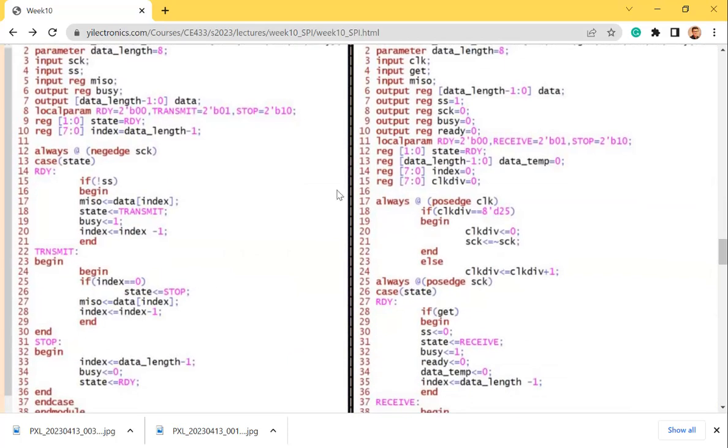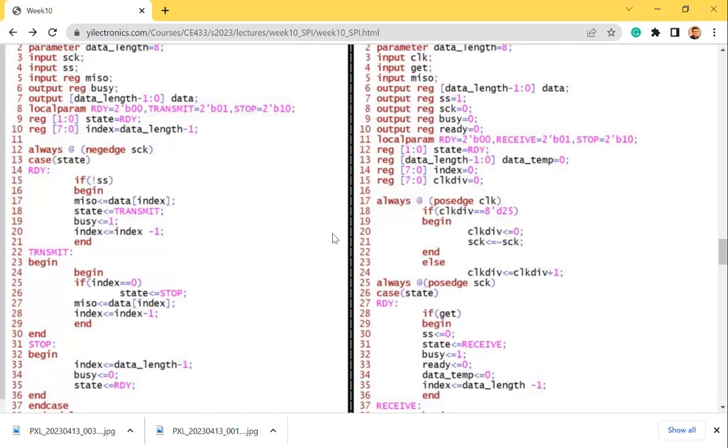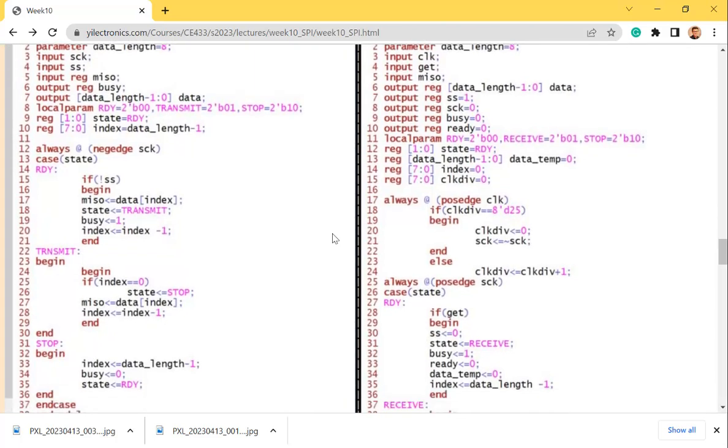So what should this one be? Leader receiver and follower transmitter, right? So for this light sensor, which one are we going to use? If you look at the board, the designer didn't even bother to put an input in there. Is this one receiving anything? No. It just sends the light intensity out, right? So this should be a follower. Why is it a follower? Why is it not a leader?